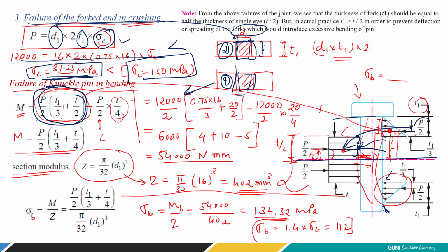So the force applied is P by 2 and we want to find out the dimensions, that is distance. Moment क्या है? Force into its perpendicular distance. यहाँ पे F क्या है? P by 2 है. क्यों? Because we are considering the half section, right? So we are dividing the load in 2 portions because it is simply supported.